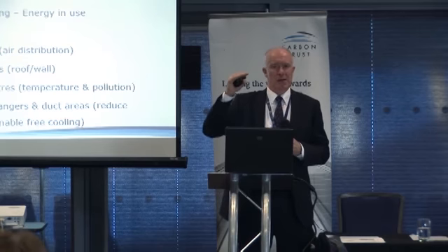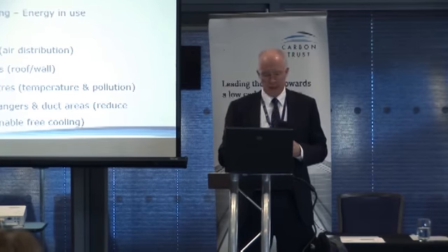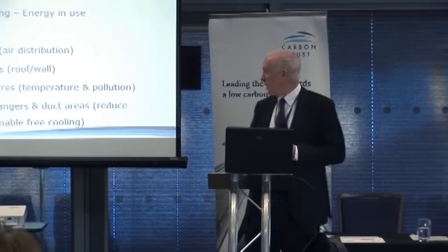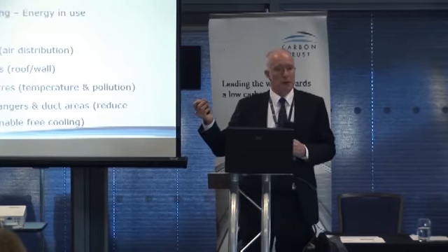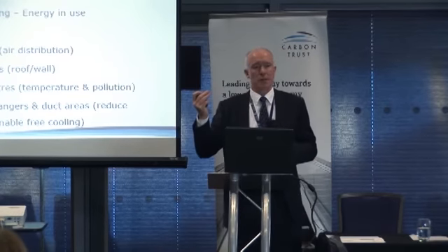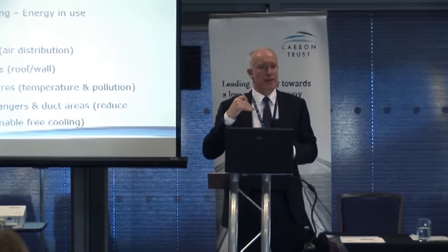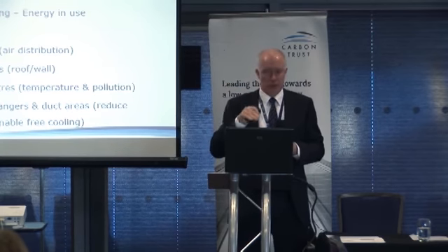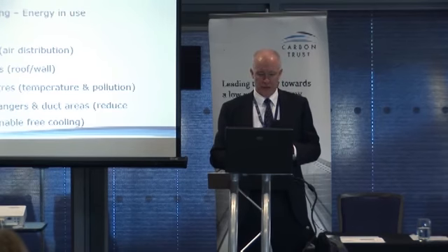If there's low ceiling height, it's going to need a lot of fan power, and it's going to stop us using free cooling techniques. Also, what is the access to outside? Is there easy access so we can put free cooling plant or refrigeration plant, whatever we're doing, outside? Or, particularly, bringing in ducted air, can we bring ducted air to it? Very often, computer centres are located in the centre of buildings, and it becomes quite difficult to do.